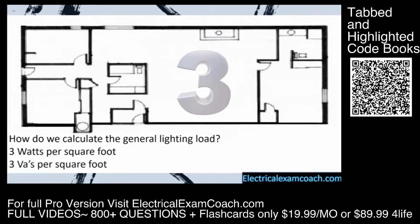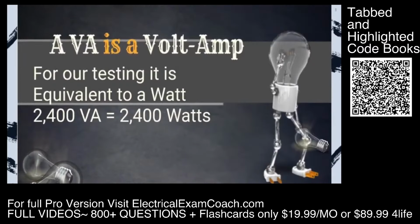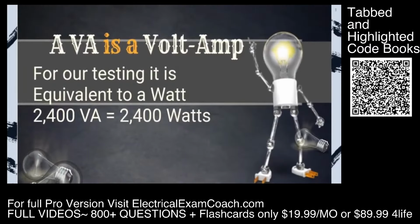But the code language actually uses VAs. So 3 watts per square foot or 3 VAs per square foot. But the question is, what is a VA? A VA is a volt amp, and for all of our testing, it's equivalent to a watt.